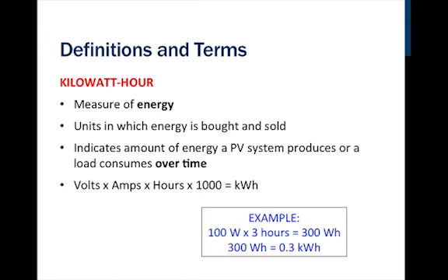A kilowatt hour is a measure of energy. So we have watts times time, and we get kilowatt hours or watt hours, depending on what units we're working in. So this is now power over time, power times time. This is something that's real. This is how we buy and sell electricity. And so our home is going to consume X amount of kilowatt hours per month, and our system is going to produce X amount of energy per month or a year or a day, and that's going to be in kilowatt hours per day or month or year, depending on what units we're in.